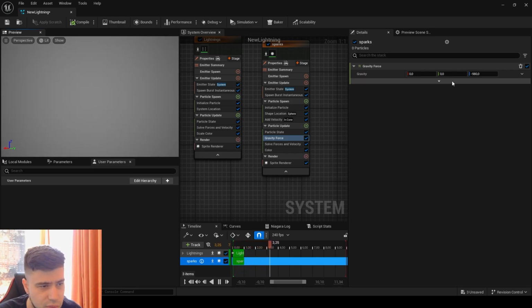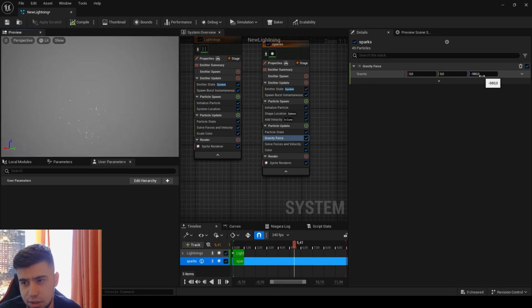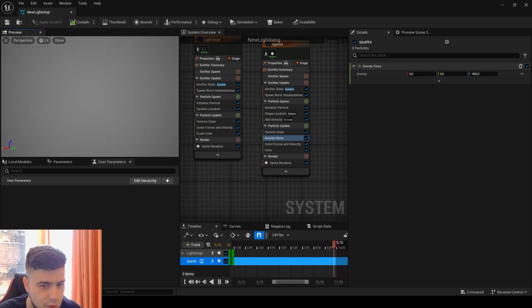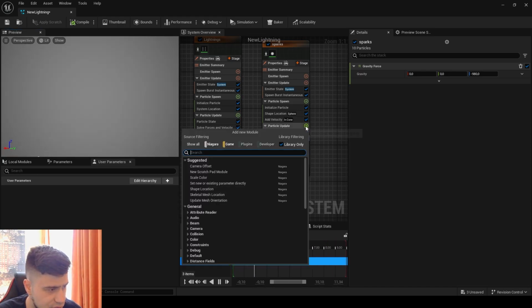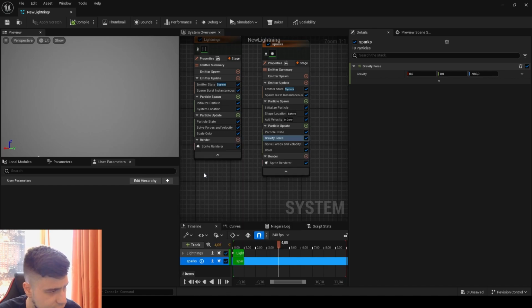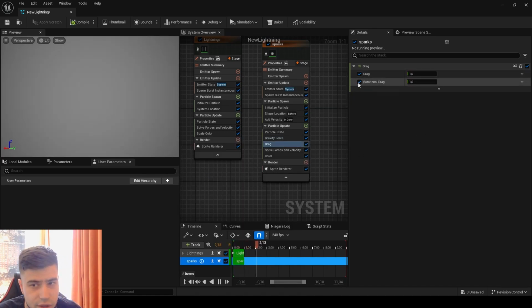So the gravity has to be by default minus 980. So we will keep it like that. We'll continue now with drag. So the drag is the friction which we're giving. So let's add a drag and keep it to 1. Here the rotation drag, I will stop it. And now let's see. Okay, now it's more like an explosion.